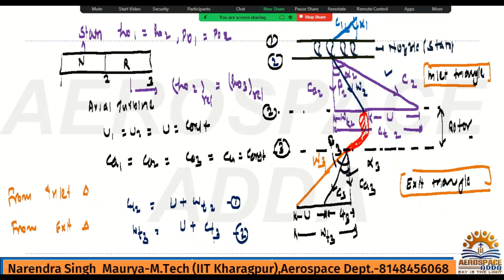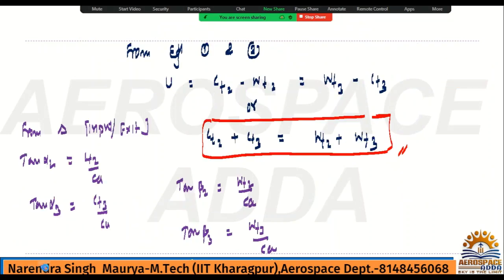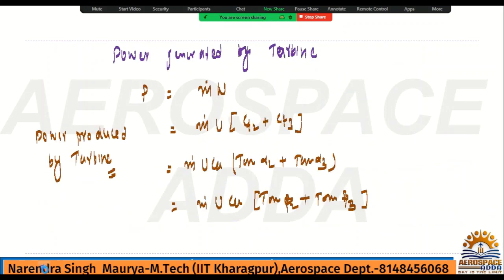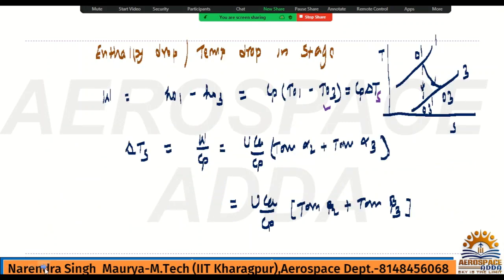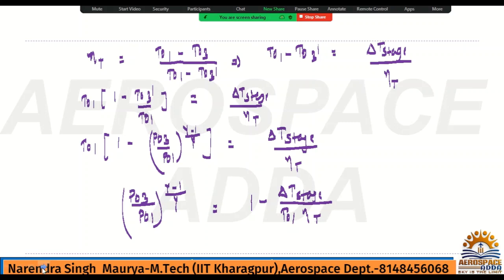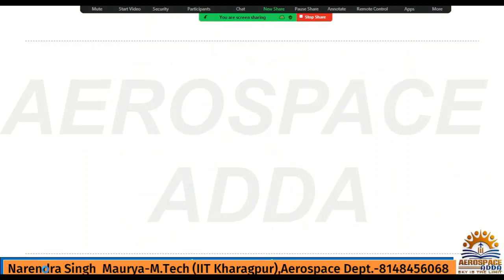So this velocity triangle and this velocity triangle what I have drawn here, it is the same, there is no difference. The thing is they have used a different manner to draw. So at least you should have a proper visualization. Whatever the velocity triangle they give to you, you can identify, and you can use the formula based on that. Sometimes they will change the angle, okay, so whatever the required angle you can write on your own. I mean, suppose somewhere it is measured from the horizontal side, and it is measured from 30 degrees. So from the vertical side it will be 90 minus 30, which is 60. So accordingly you can change also. So for that reason I am giving this triangle.